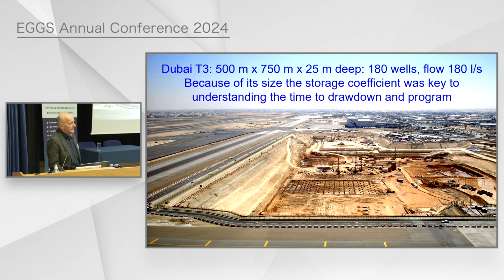A bit of an admission here, I don't pay much attention to storage coefficient. So sigh of relief from the geotechnical engineers who've never really understood it, howls of horror from the hydrogeologists who are vested in it. But the reality is that almost all the dewatering systems that we do, we can dewater it quicker than it can be excavated.